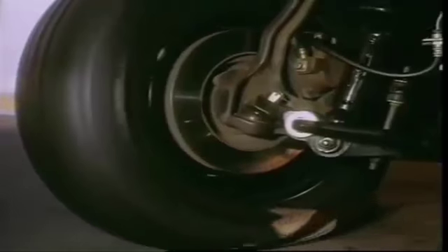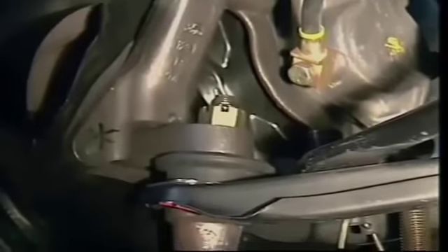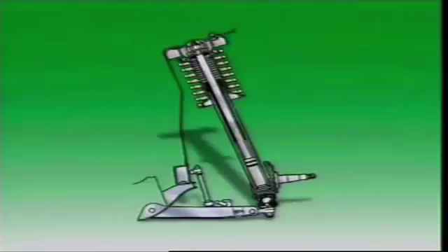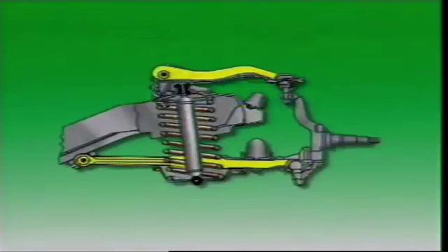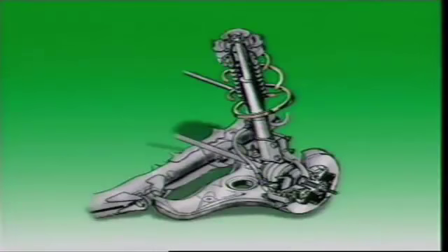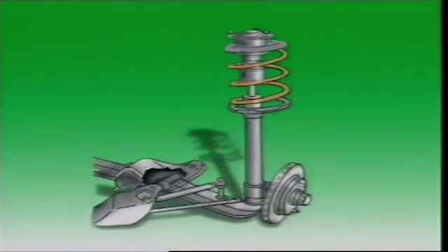The arms must be strong enough to withstand the forces due to normal operation, but light enough to minimize the vehicle's unsprung mass. The front suspension can have 1 or 2 control arms. Parallel link front suspensions have 2 control arms. Vehicles with strut-type front suspension have only 1 arm. It can be a wishbone shape with 2 fulcrum mounting points, or straight with single fulcrum.